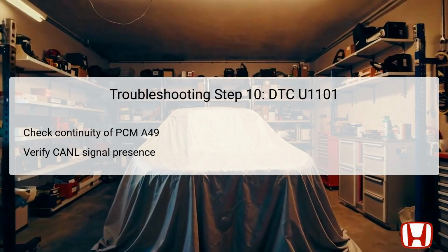Next, continuity checks are performed between PCM connector terminal A49 and the engine mount control unit 16P connector terminal number 12. This test is critical for verifying the functionality of the CAN-L signal, which plays a complementary role to the CAN-H in data transmission. Confirming continuity here ensures that the communication link remains intact and operational between the two components.